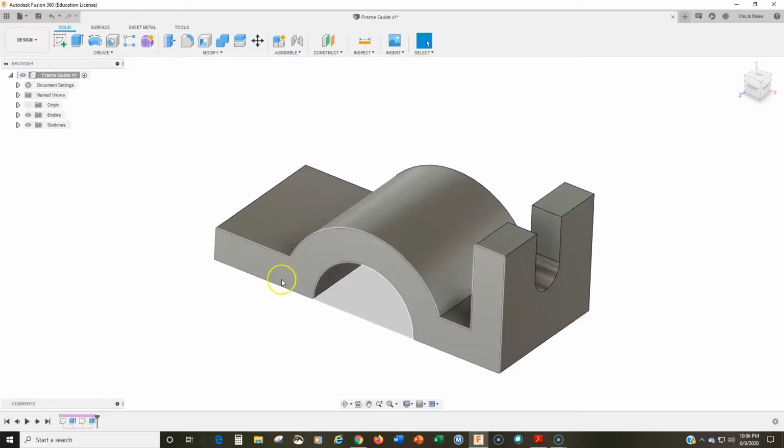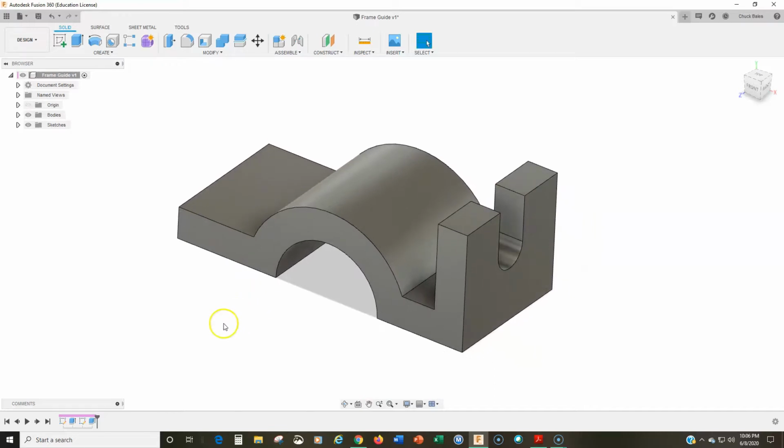What I'm going to be looking for is that your model is very efficient, that you have a sketch and then an extrusion or a revolution. In this case, it's all going to be extrusions. There's not any additional bodies that you've hidden. Hiding bodies is wrong. There's not any extra bodies that somehow are hidden, and you don't have some sketches that you've decided you're not going to use. All your sketches are fully constrained, so there's a lock on each one of these, in addition to all the features, right?